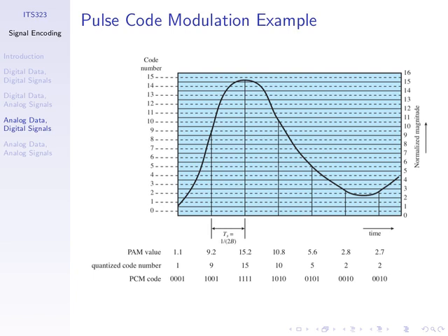What's happening at the receiver is we receive the digital data. We need to play back some audio. So what we do is we generate some output, and that's sent to the speakers. An output at a particular level, and the next sample period will change the output according to the bits that we receive. So value 1, let's produce an output at this level. If we have 0, 1 up to 15 there, we produce at the receiver an output at this level and hold it at that level for the sample period.